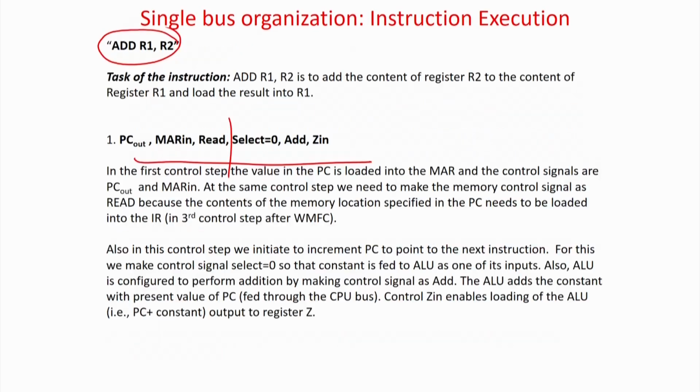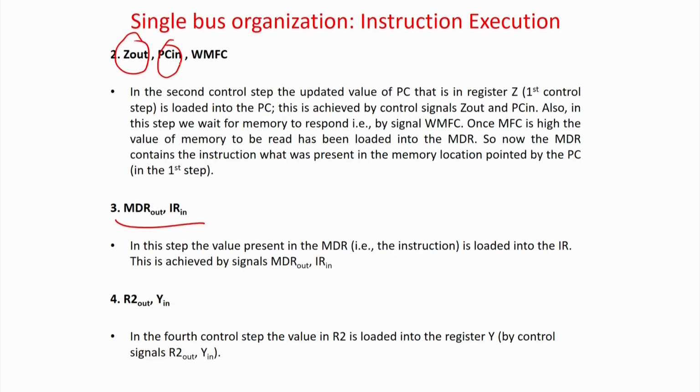That is, the first stage points to the memory location where the instruction is stored, plans to increment the program counter, really increments the program counter by the ALU, dumps it in PC and waits for some amount of time. Once it is done, take the instruction from MDR and put it in IR.